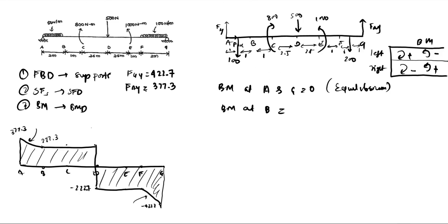So we have a bending moment at V, which we can calculate. This is our cross section at V. We can calculate either from the forces on the left, which is the two forces, FAY and this 100 force because of the UDL, or we can consider all of the forces on the right. We will not do that because it will just make it more complicated. So we will consider forces on the left. So on the left we have FAY, which is